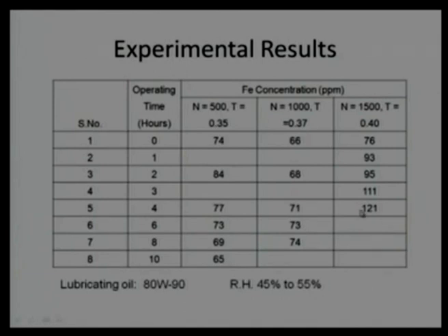This means more and more corrosion happens to the surface, even though we know the gear lubricant additives are known to be very good gear lubricants, and still we are getting this kind of wear particles. That means the gears will never work in the hydrodynamic domain, never in a fluid film lubrication mechanism, but in mixed lubrication or boundary lubrication.